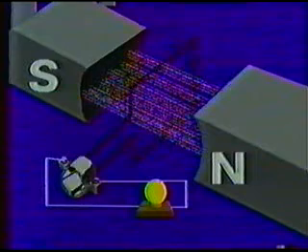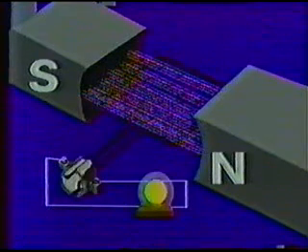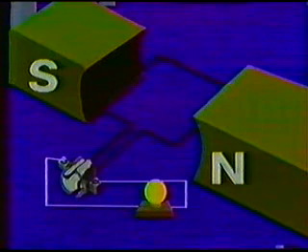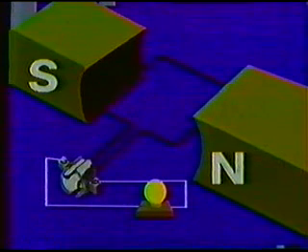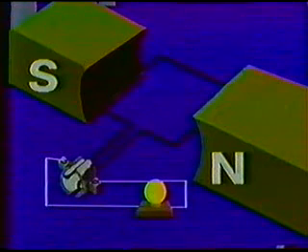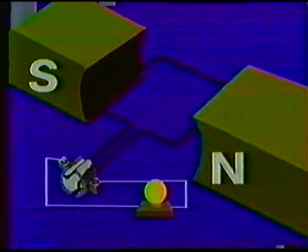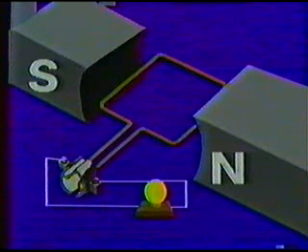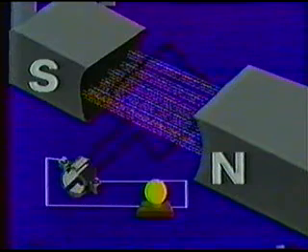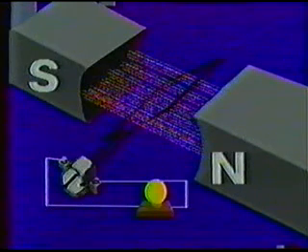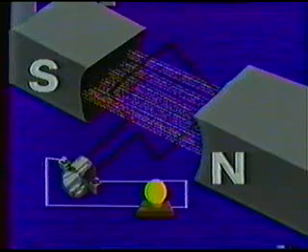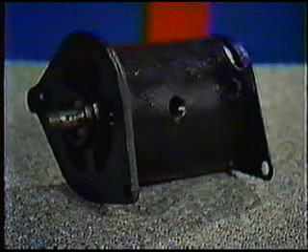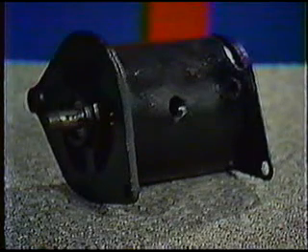But there are several problems shown here that make a device this simple impractical. First, using a permanent magnet to produce our field of magnetic flux is not workable. The weight would be enormous, and there is no way to vary the amount of flux that is produced by the magnet. Our conductor will only produce any electrical current once in an entire revolution. And we have no way to control the output of our simple generator, other than by how fast we rotate the conductor, or armature. Let's look at an actual generator to see how these limitations are overcome.